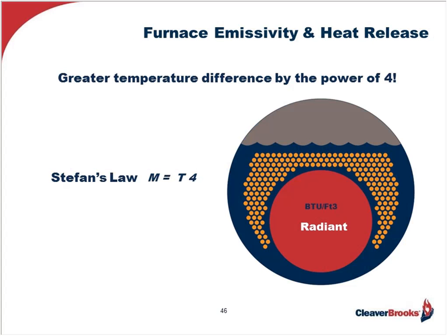Focusing on the radiant heat transfer, it occurs in the furnace and is any surface which actually sees the flame. It's also the furnace, that is, the area for the greatest amount of heat transfer, mainly because of the significant temperature difference between the fire side and the water side. I mean, you're looking at over 2,000 degrees in the furnace and a substantially lower water side temperature. As a matter of fact, the furnace is at the power of 4 greater in temperature difference.